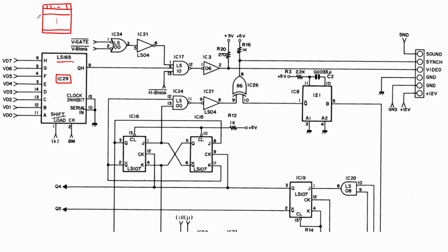And the way this works is that the character generator will take each one of these 8 bytes, each one of these lines, and send it to the shift register along these 8 lines, VD0 to VD7. And these 8 bits will be loaded in parallel load, into an internal register of the shift register, which has this name for a reason.